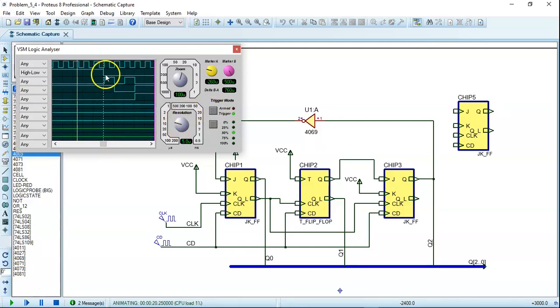So look at this. The system is starting at this falling edge of the clear direct signal. Now the system exists, and you've got, this is the Q0, so Q0 is a kind of a square frequency, but only 2 pulses, you see. And then the Q1 is just another pulse. It goes down for two periods, and then the Q3, the Q2, you know, is low all the time and then go high, and in the end the circuit does nothing else.